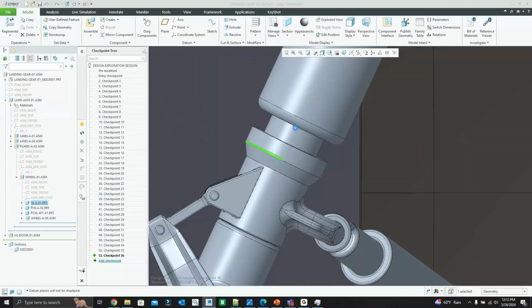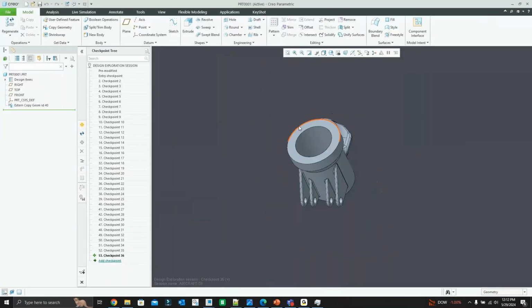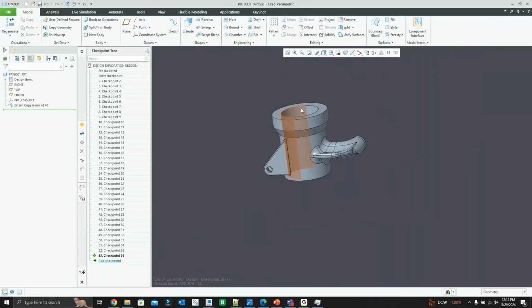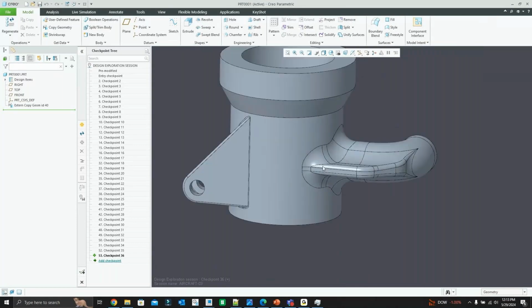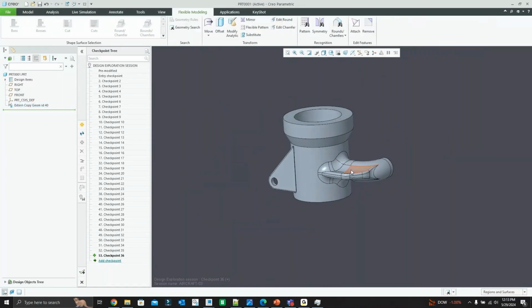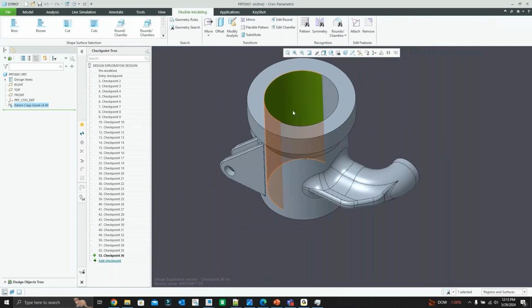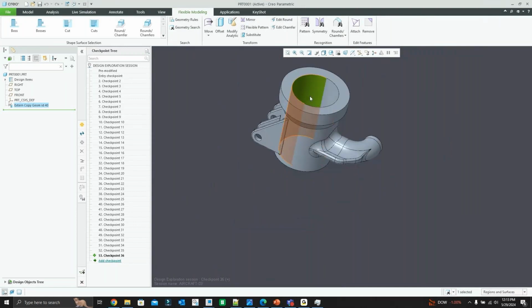Okay, so I'll select this component now. Okay, great. So one thing that happens sometimes, like when I'm 3D printing, I have a Bambu X1 Carbon. I also have a Creality printer at home. Is sometimes I just want to test fit for things, and I don't need all the features in a particular part. So, for example, this extrusion on the right side here, I don't really need. So what I would do is I would just say, hey, you know what, I just want to test the fit of this. I want to print this out and see if this radius works for me, and the component that fits inside of this will actually fit, right?